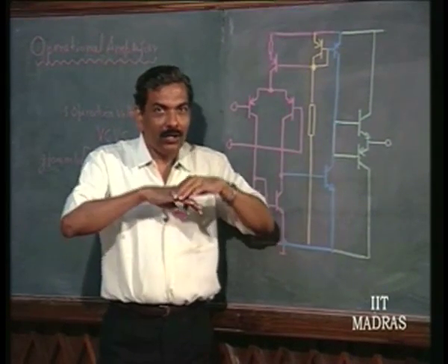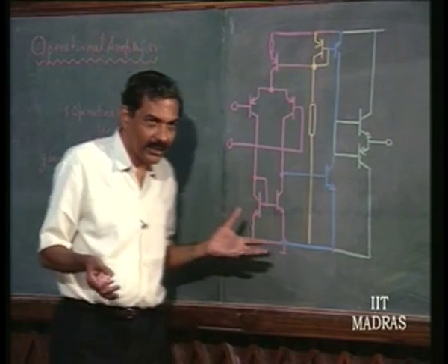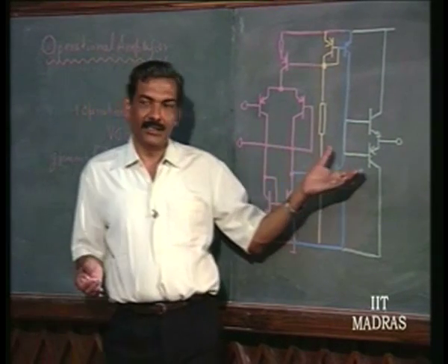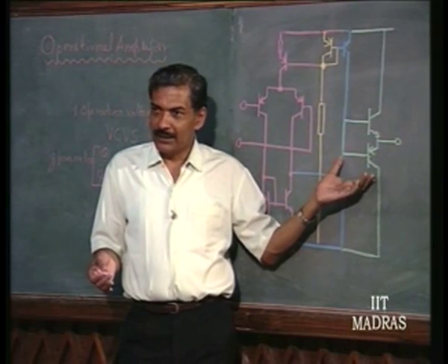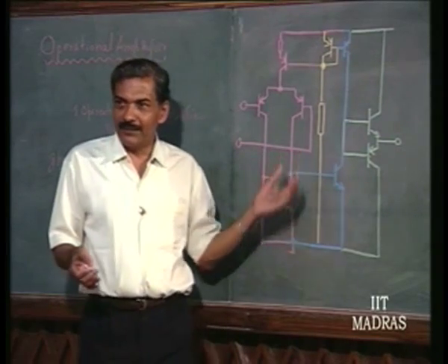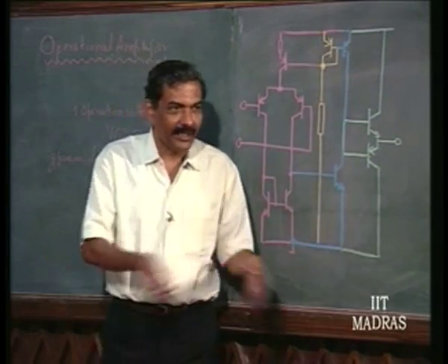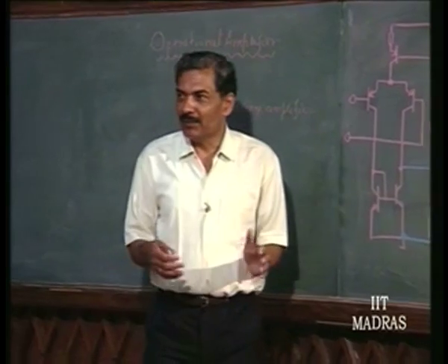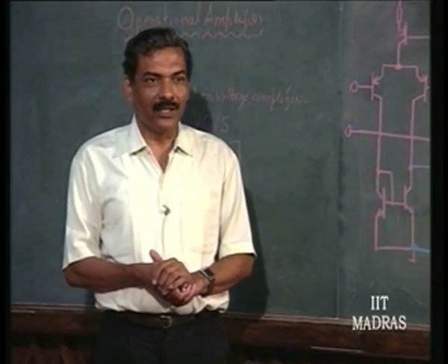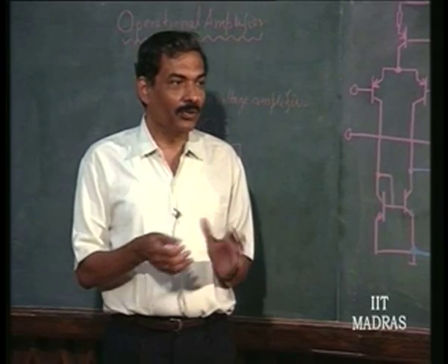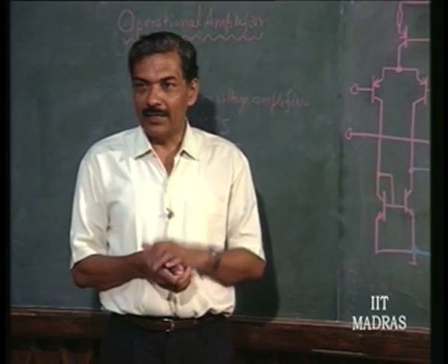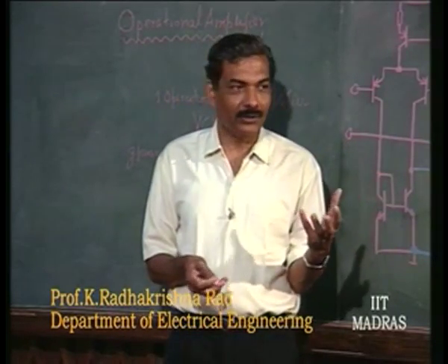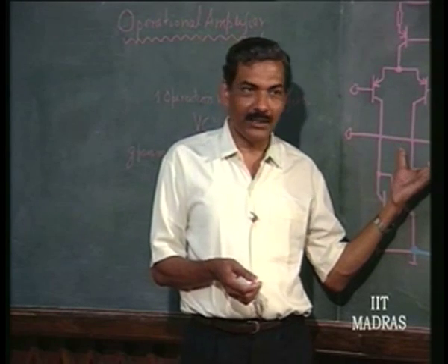So, what is called the third generation operational amplifier is a slow process of evolution. People did not come to this conclusion of freezing the number of stages to 3 in one shot. They tried different combinations. The first tendency is simply to cascade as many stages of amplifiers as possible. That resulted in severe problems of high frequency oscillation and also this common mode problem resulting in latch up problems, etc. So, the user had several complaints about the op amp being not suitable in certain applications, etc.